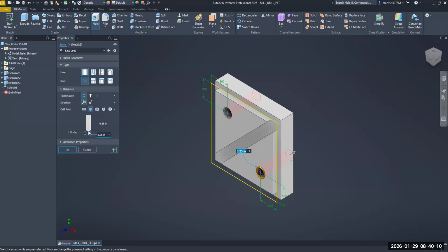Also, Mr. Morris does not want a drill point. See, that's a drill point. I do not want that. So make the drill point flat. And then I want you to change this dimension right here to 0.125 because we're only going to go down 1/8 of an inch thick. The end mill is. And then we're going to select OK.